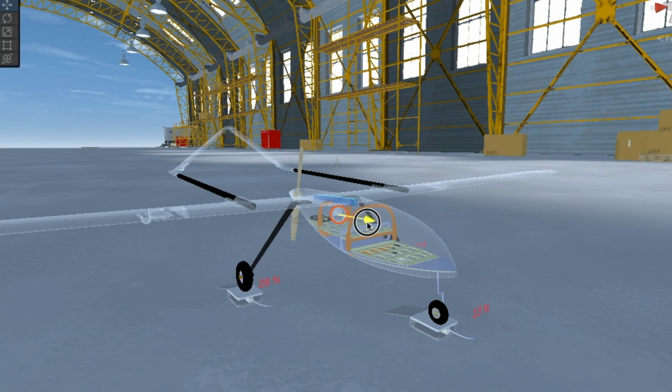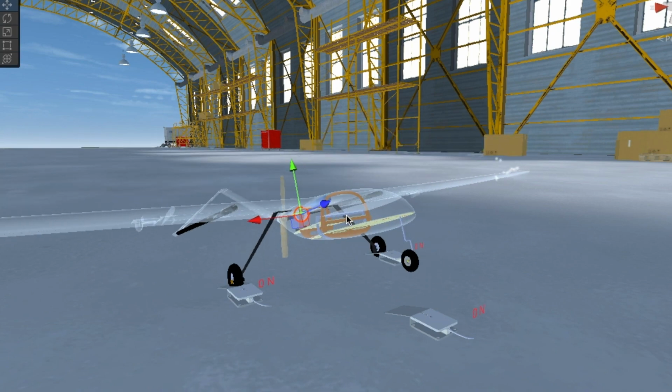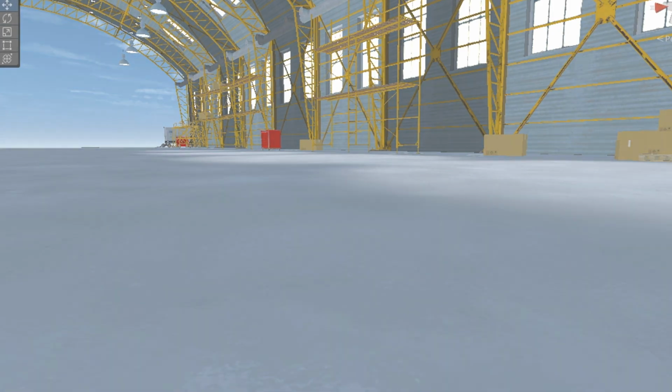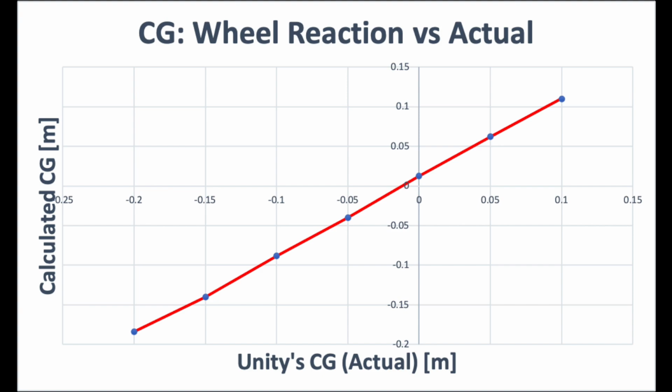As mentioned previously, it is important to consider the mission objective when selecting the appropriate CG position within the recommended range given. Additionally, it is worth noting that the neutral point is approximately located at 50% MAC, and for flight testing purposes, the default CG position is typically set at 35% MAC unless specified otherwise.